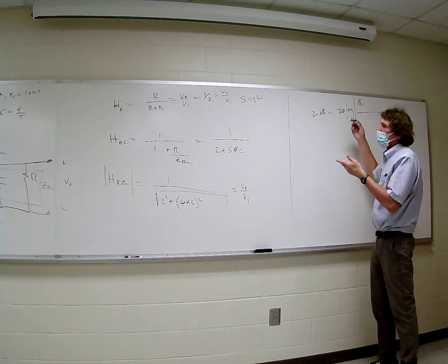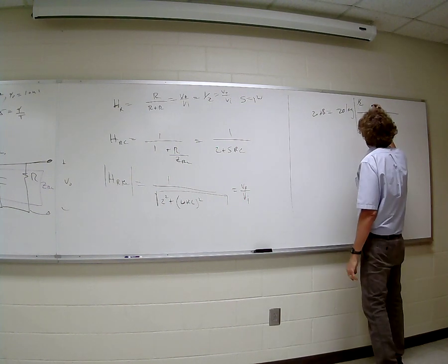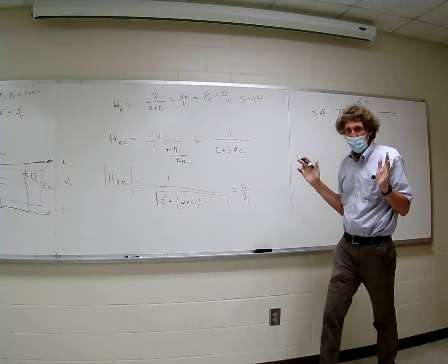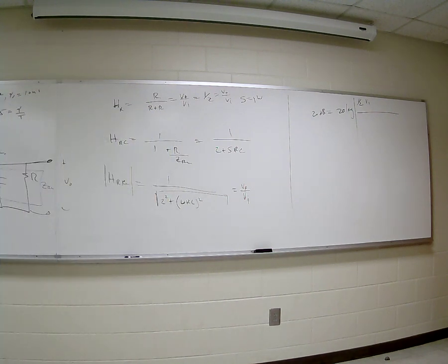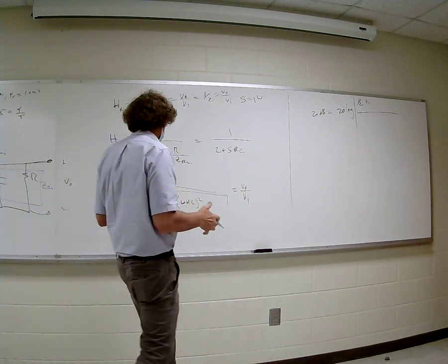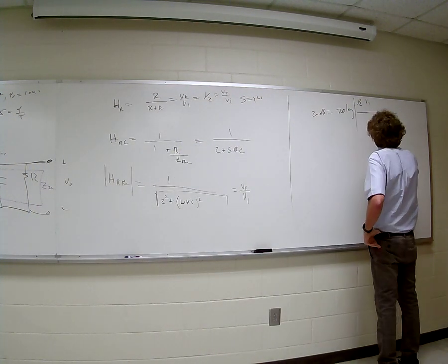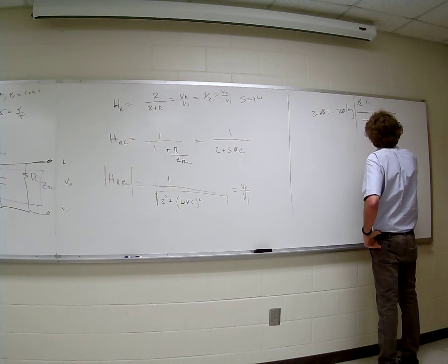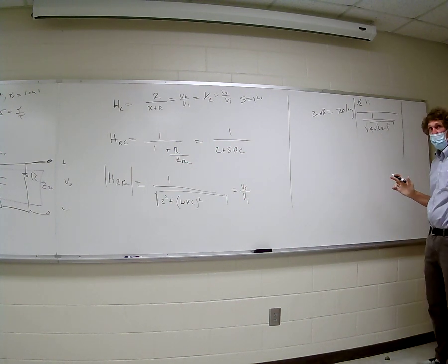And if you want to think about, well, that's not the output voltage, multiply 1/2 by Vi. Do you agree that would be the magnitude of the output voltage with no capacitor added? Agree? We want that reduced by 20 dB, so we divide it by that guy, which is going to be 1 over the square root of 4 plus omega RC squared. Now just listen to me on this, right? Are you with me so far with what I've done?